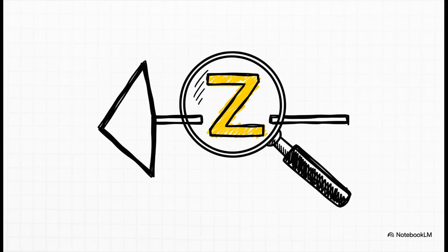Now, because it's such a unique and absolutely vital component, you definitely need to know how to spot it on a schematic. A normal diode just has a straight vertical line against the triangle. But for a Zener diode, you want to look for the distinct Z shape on that line. Those two little bent arms clearly dictate to anyone reading the plans that this isn't just some simple one-way valve, it is a precise voltage regulator.